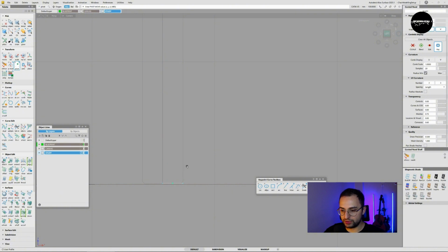Holding Ctrl and Shift and the middle mouse button, I select the move tool here, and I hold the Alt and Control keys and left click to make that pivot snap to the end of the curve. So I use Shift and Control and scale on the Y axis to capture more or less the width of the leg. Yeah, is it clear so far?